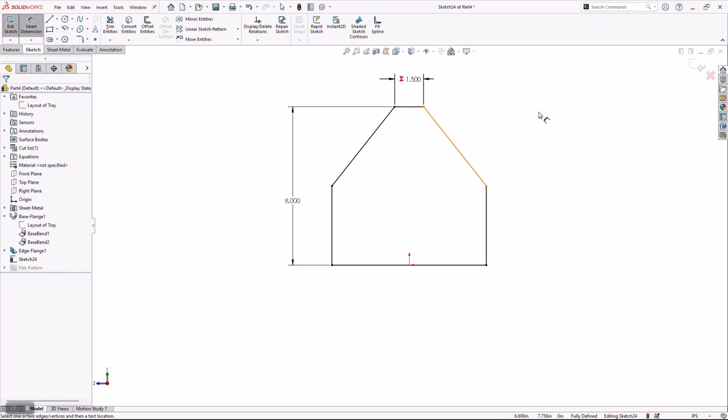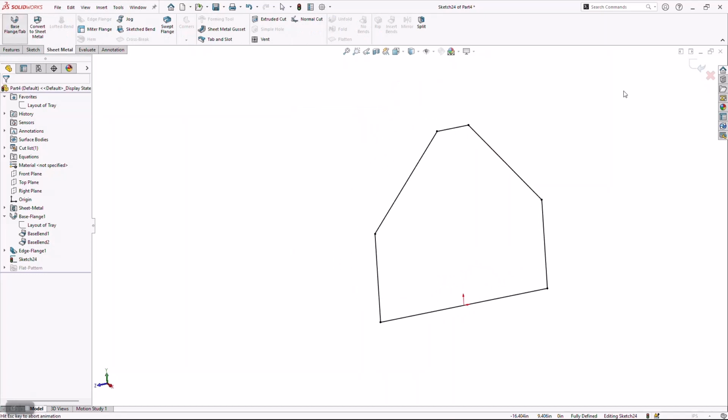So what I have done by setting up those variables up front is I'm giving myself that ability to call that value in multiple locations. In this case, I'm calling it not only in multiple locations on a single part, but you're going to see on actually multiple parts that are in context to each other. Now I'm ready to turn this into a piece of sheet metal.